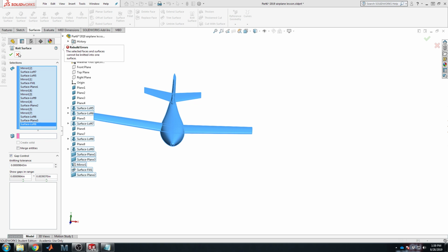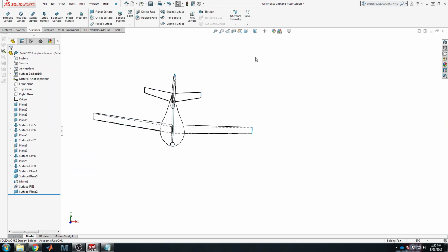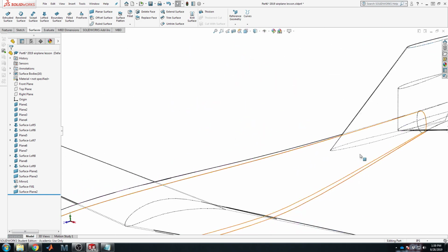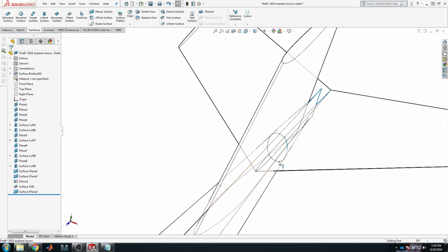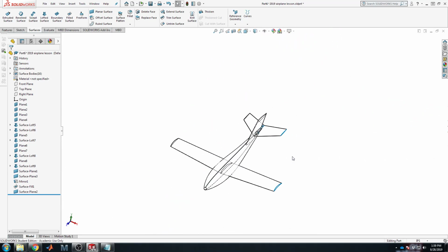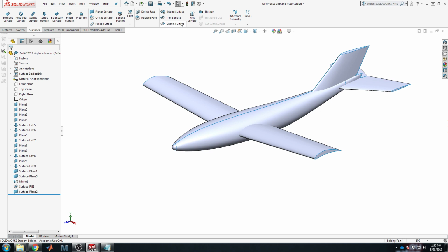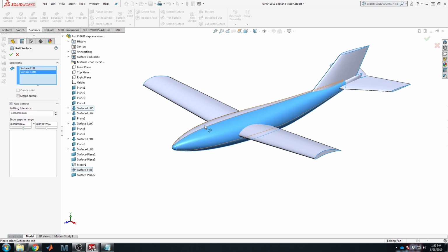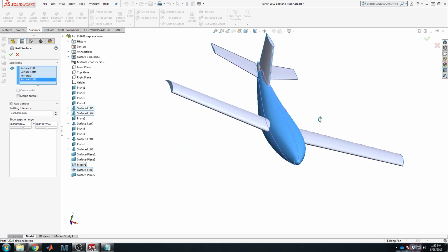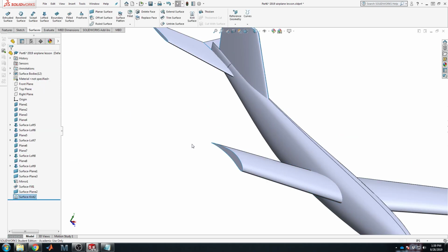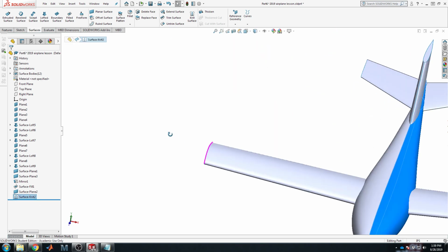And the reason you can't is if you really look in a transparent sense, you still have the wing going through the center of the fuselage, you have the vertical tail going in, then ending in empty space, you have the horizontal tail chunking through it. These are what are called non-manifold surfaces. They don't have just a single surface. It doesn't have a nice way to intersect things. So what we can do at first is think a bit more strategically where we'll knit together the fuselage, because really that creates one sealed component that we want to attach things to. So let's go ahead and knit that into one piece, making sure I've only selected what I want.